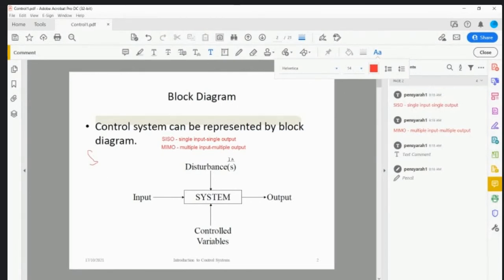Instead, we just focus on one output and one input, meaning we represent the system as a SISO, so that the controller will become simpler, instead of having a complex controller. It is a very good practice to have a simple controller dedicated to one function.